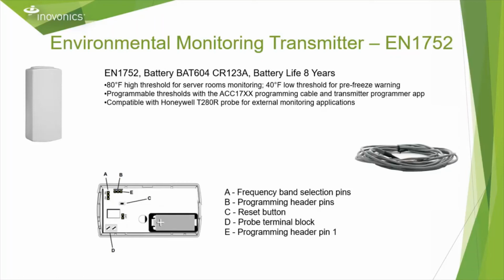The EN1752 has an 8 year battery life, can detect temperature from 80 degrees Fahrenheit as the high and 40 degrees Fahrenheit for the low, and with the ACC17XX programming cable, it can be programmed with customized high and low temperature thresholds. The EN1752 is compatible with the Honeywell T280R probe for external monitoring applications.